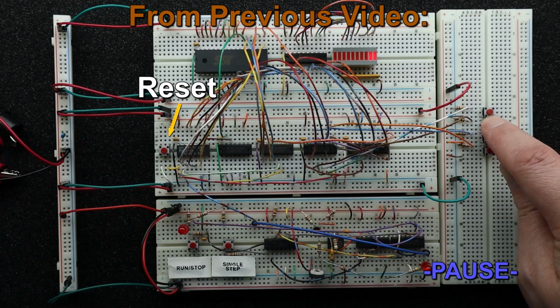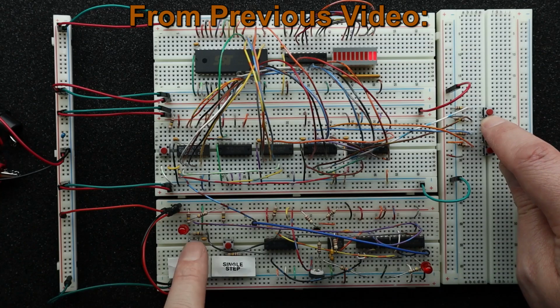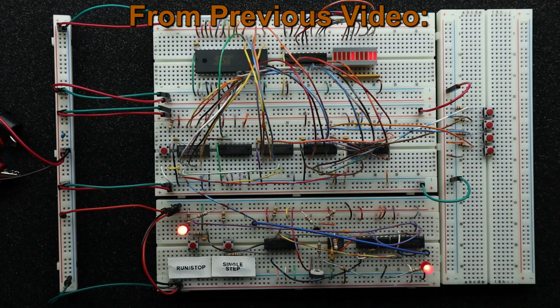But what we need to remember is that there is a propagation delay from when the decoder was enabled to when the decoder output a high on its output pin. The register IC was taken out of reset when the reset switch was released, but the decoder IC needed a propagation delay before it went high, so that gave the register enough time to clock in the output from the adder, which was 3. Then, from there, the clock never transitioned from high to low during the remainder of the add instruction, so the value of 5 never got stored.